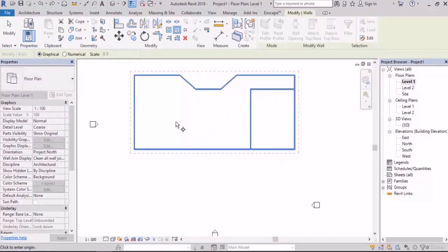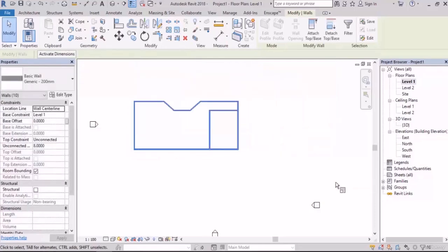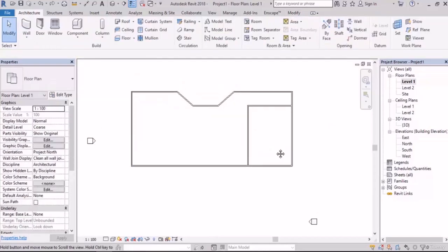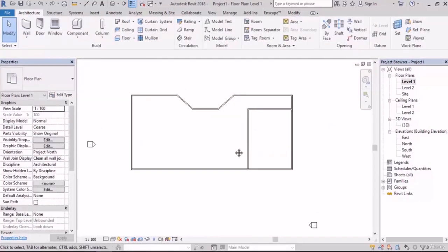The first step is to click on the 2 points of the wall that I want to have a specific size for. For example, I said this wall and I click on 2 points. The second step is to enter the size. How much is it going to be? 25 meters. Enter. No matter how much it was, now it's 25 meters. One more time.